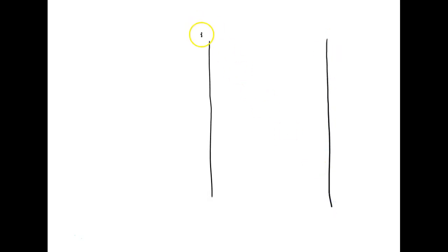And this is, if you remember, so we start off with what we call a ladder diagram, right? Generically we call this L1 and generically we call this L2. And then we draw circuits between L1 and L2. Now AC means nothing because AC has no polarity, because it's constantly swapping. But DC has a polarity, right?